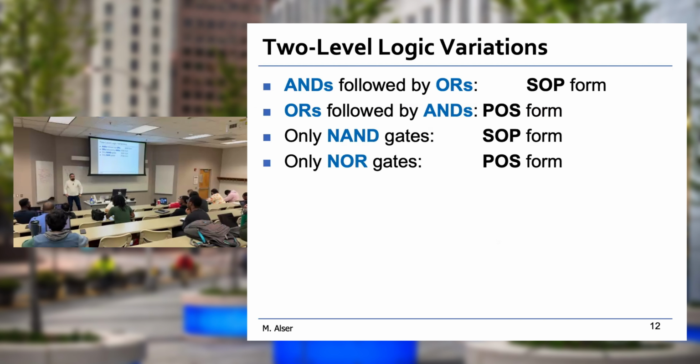All right. So this slide, I don't like to try to remember or make a rule for this circuit. It's better to understand how it works, and then it's easy for you to apply it for any scenario. But just as a matter of fact, whenever we talk about sum of products, then it's always drawn as AND gates followed by OR gates. I don't like this way of explaining it, but it's really much better if you understand what you are doing, and then you will get this structure really easy from the equation itself. Because we said sum of products means the terms are added together, right? And each term, there's a multiplication in it. So you would know that there is an AND gate followed by OR gate,